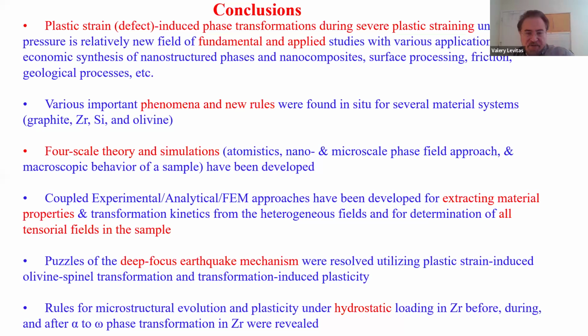Okay, how does this compare to shock-induced amorphization? Well, it depends. If this is plastic strain-induced amorphization, its mechanism should be very close, but there is an additional effect of strain rate, which we plan to study, not, of course, up to strain rates in shock, but up to 10 to the 3 to 4. At the moment, we don't have this information.